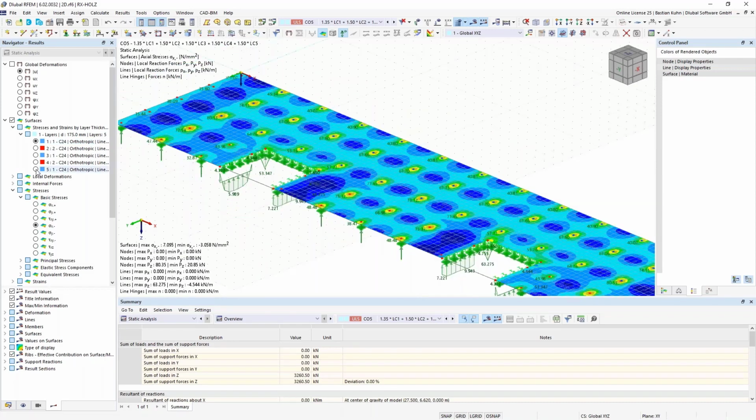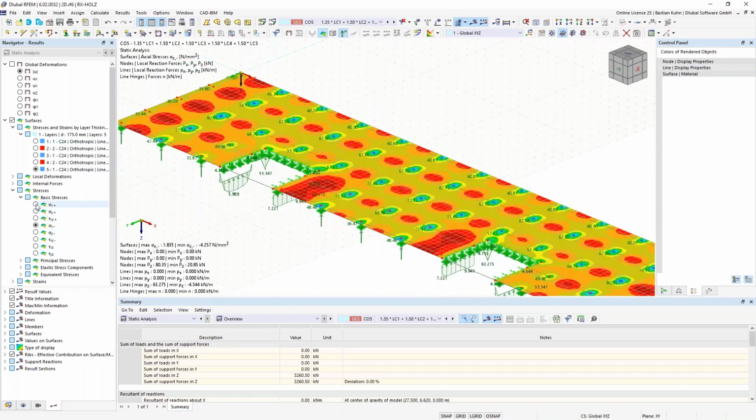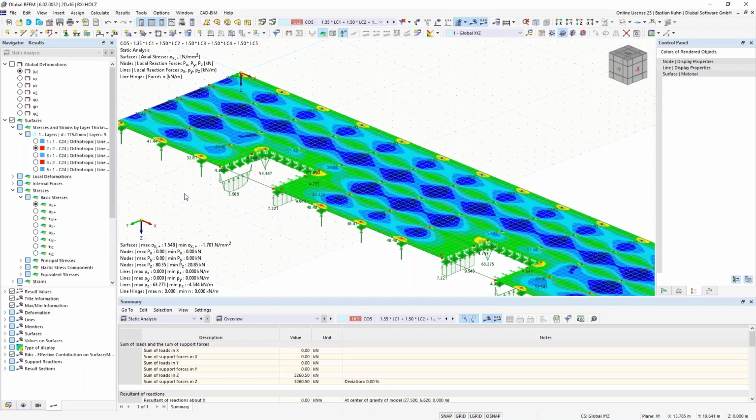If you go to the bottom of this layer, you have to change the origin. You see that there you also have the 7, and you can actually see how the stresses change there. Where you have a high stiffness, you have a stress in this direction, and where you have a low stiffness, you remember that we defined the stiffness in y direction there with nearly 0, you have less stress. So that's for the bending stress.